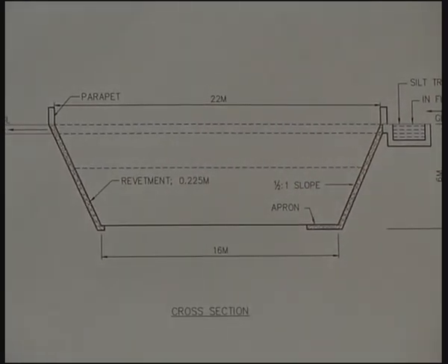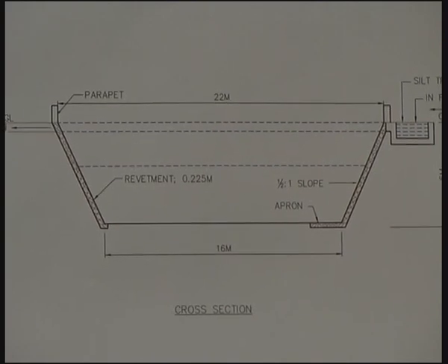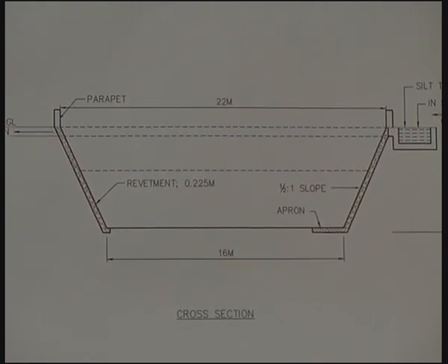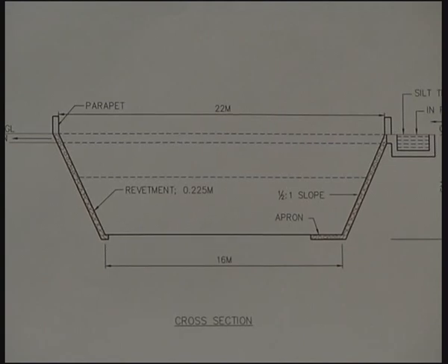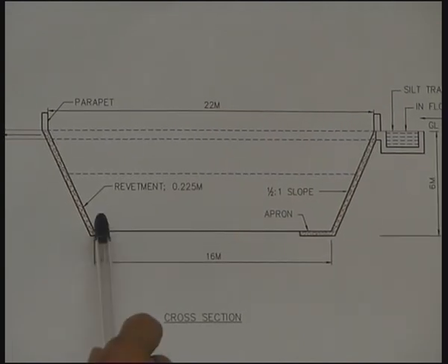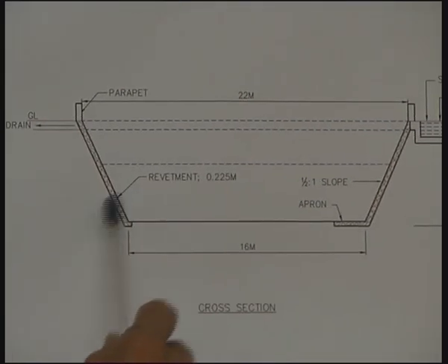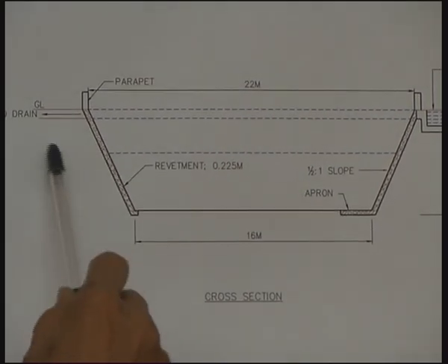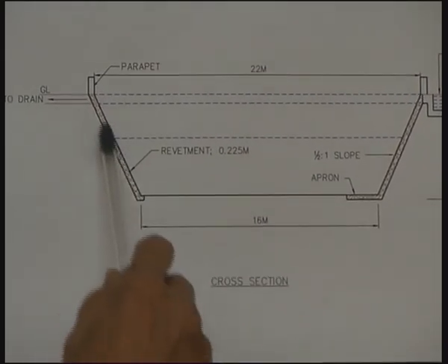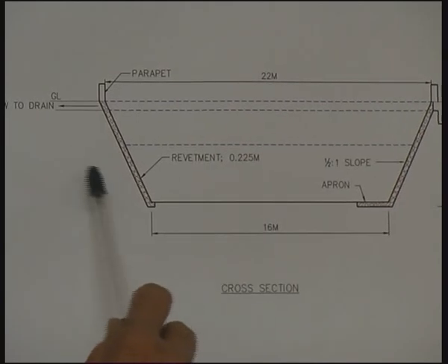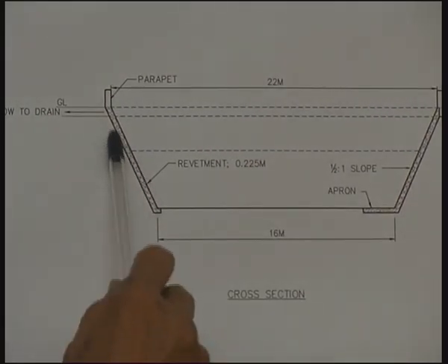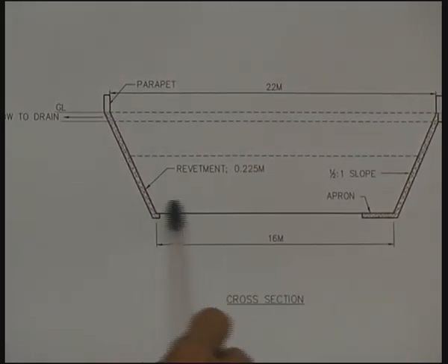Even in the house premises, the rough stone used is just dry and without cement. So therefore, it is possible that water can seep through without any hindrance. The purpose of this revetment is to retain the sides, otherwise the sides may collapse and it will silt up here.